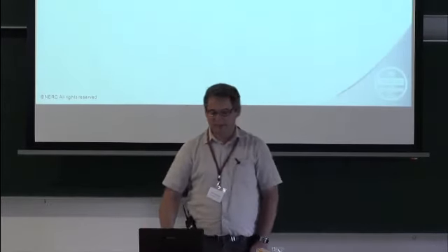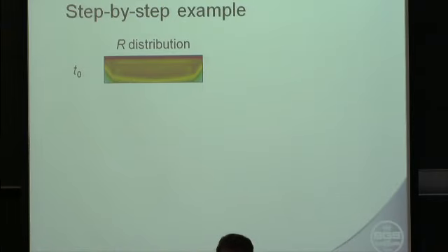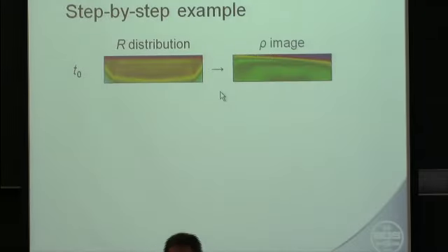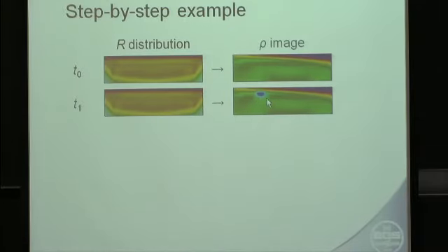And this is just a simple example of how the focusing procedure would happen. We'd start off with a static optimized survey, which has this resolution distribution, and we use that to measure our resistivity data and invert to get our resistivity image. Again, the next step, we use the same survey design. We have a new resistivity image where we've got some saline tracer, a conductive tracer appearing at this injection point.